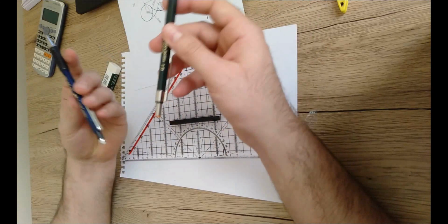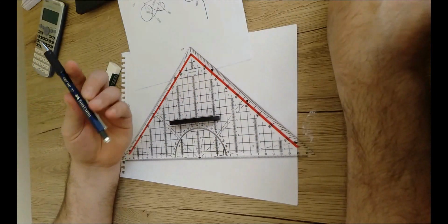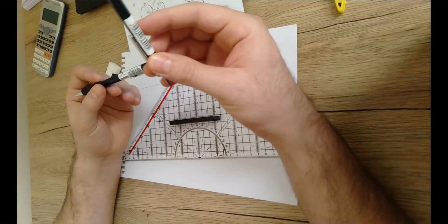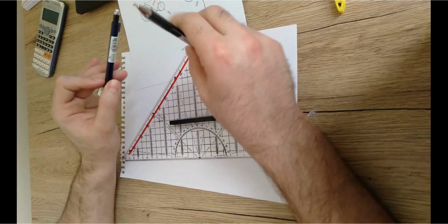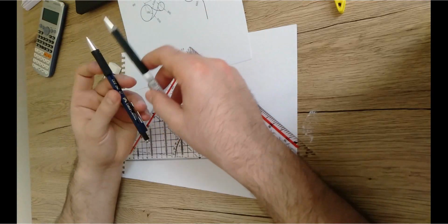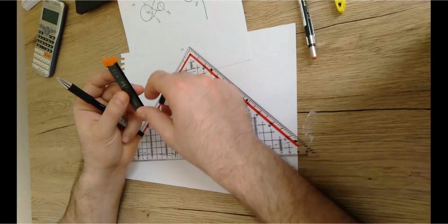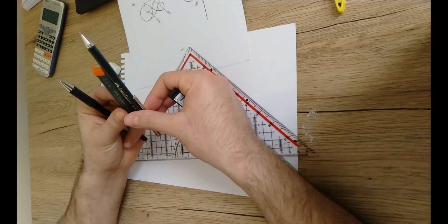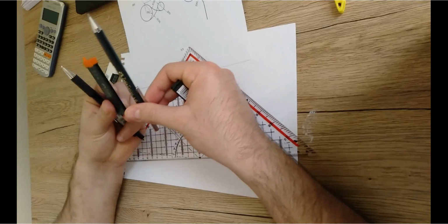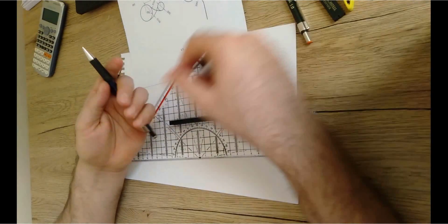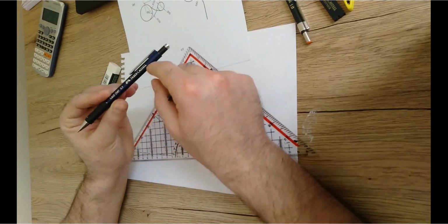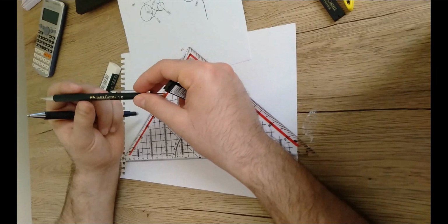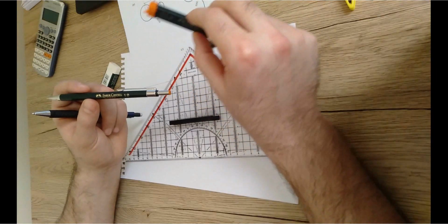I'm gonna use the 1 millimeter for finishing the drawing, but the 0.7 I'm gonna use mainly just to create the drawing. Then once I finish everything, I'm just gonna use the 1 millimeter, as I'm gonna show you, to finish the drawing. In addition to these two pencils, for the lead set itself, I'm using B for the 1 millimeter. B gives a lead that will be very clear and easily drawn, and it is kind of soft. But the hard one is preferred for the main pencil that you're gonna use as the base drawing at the beginning. For the pencil that you're gonna use for finishing, it is preferred to have B or even HB is quite enough.